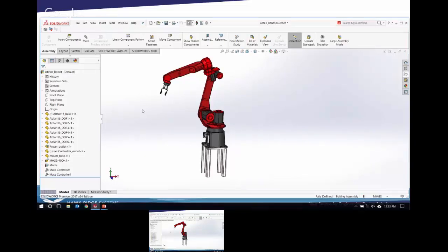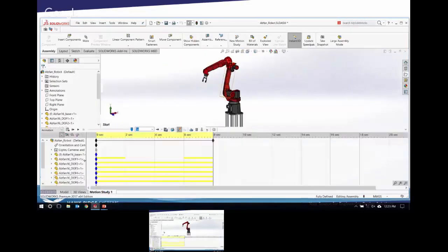David, just one thing on that I've noticed in the motion study: if you do a gear mate, those can also reverse on you. But when you're actually in the motion study, there's two choices, the animation and the basic motion. It behaves better in basic motion. Just that general animation one, it always will flip on. And when I turned it to the basic motion, the problem decreased. It didn't go away, but I ran into it less.